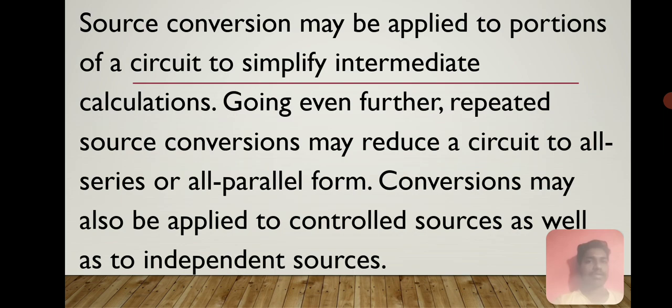Source conversion may be applied to portions of a circuit to simplify intermediate calculations. Going even further, repeated source conversions may reduce a circuit to all series or all parallel form. Conversions may also be applied to controlled sources as well as to independent sources.